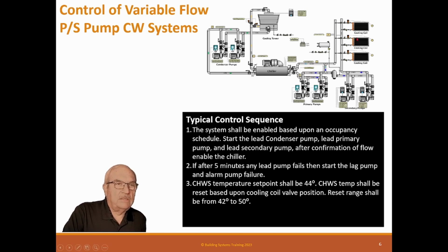So we'll actually look at where all these valves are. Now, some people used to use outside air temperature to reset this, which is an open control loop, and you shouldn't do that. You should reset it from your load, because you don't know, it might be an internal load, not an external load that's needed.